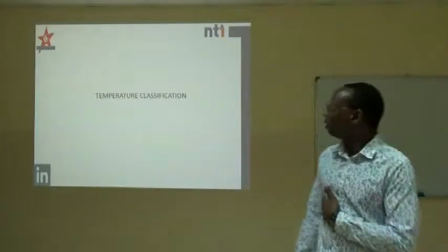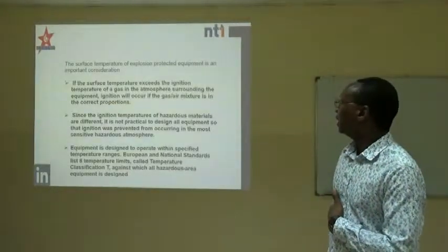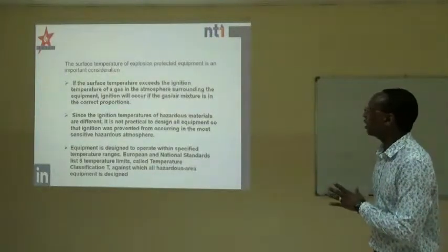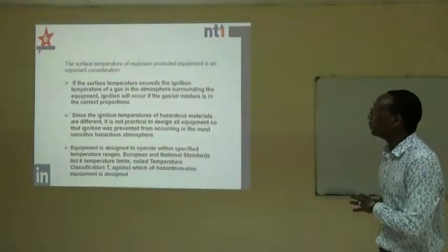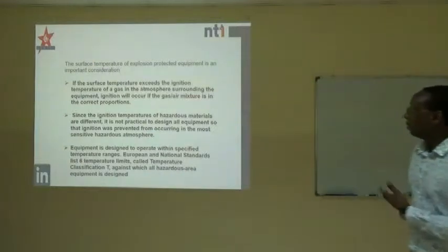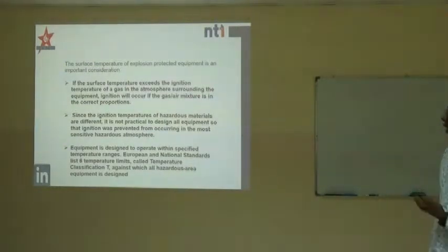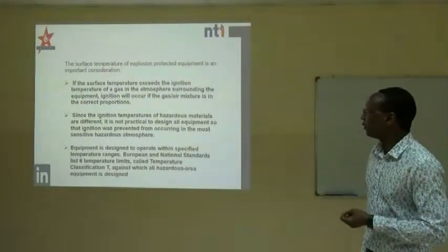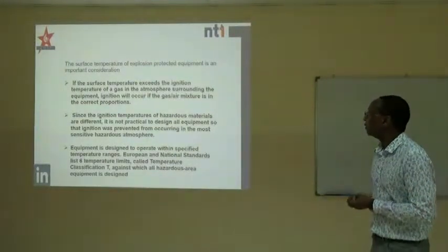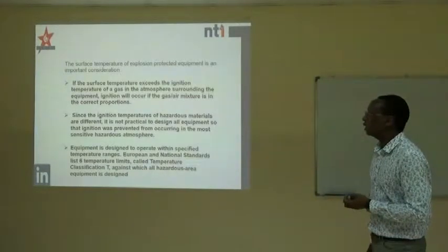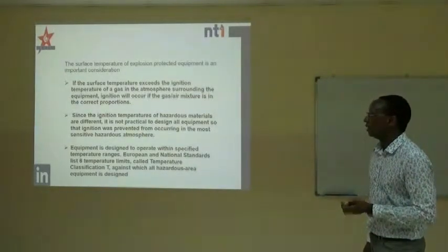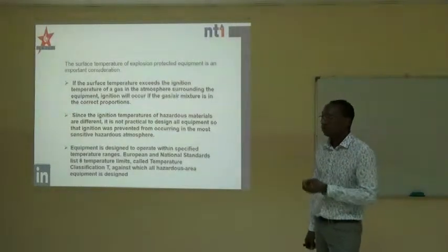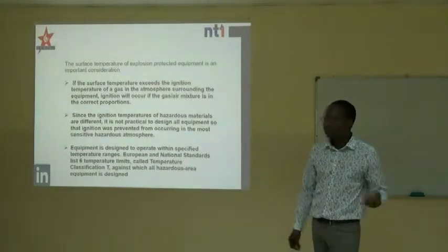I've got a table here of temperature classification, which we are going to look at. But before we do that, let's look at the surface temperature of explosion protected equipment, what it is. If the surface temperature exceeds the ignition temperature of a gas in an atmosphere surrounding the equipment, ignition will occur if the gas-air mixture is in correct proportions. Since all hazardous materials have different ignition temperatures,